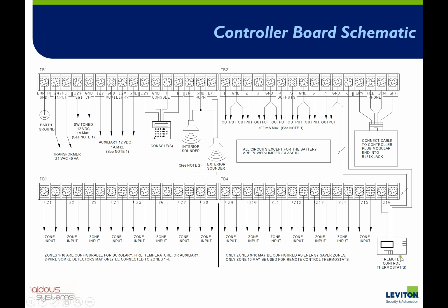Just one little side note is that if you use any of the wired thermostats, then they do wire in on zone 16 and output 8. So you do lose a zone and an output when you use the wired thermostats.